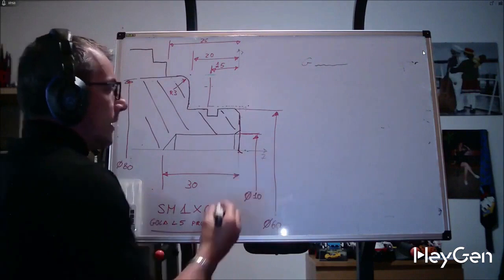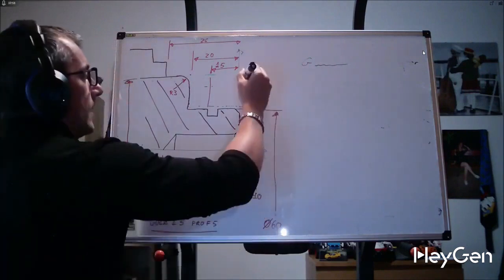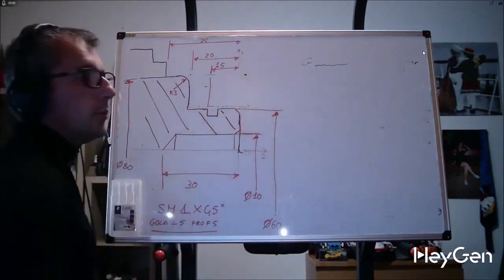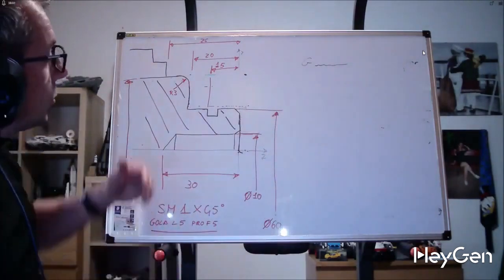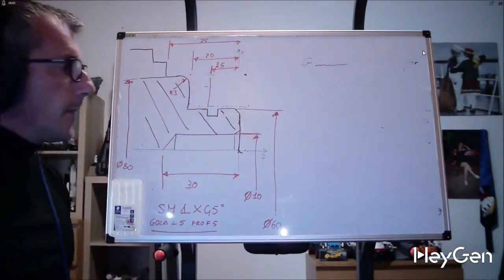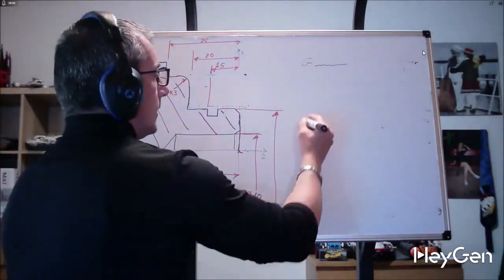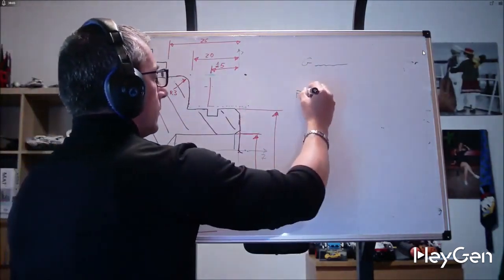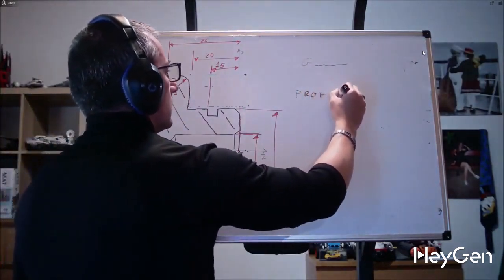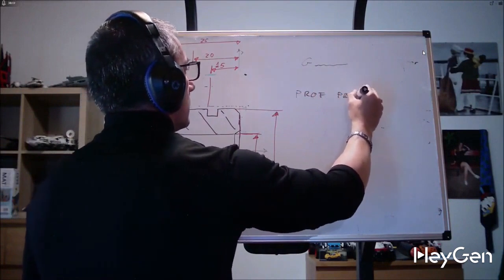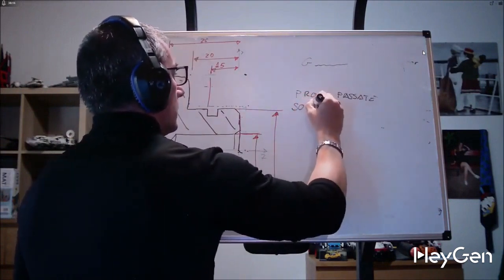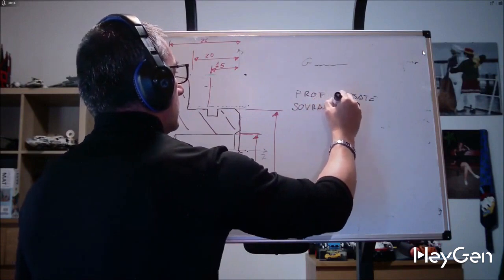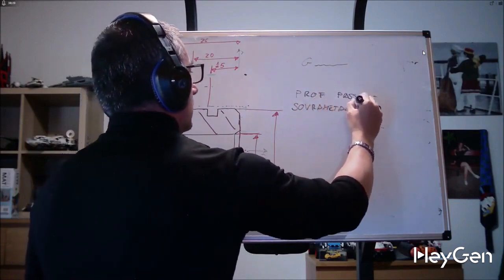After that, we will need to position our machine at a point almost coinciding with the extreme point of our blank and give our machine what? The depth of our cuts, the excess material in X and Z, that is how much excess material I will leave for the tool to finish mine.